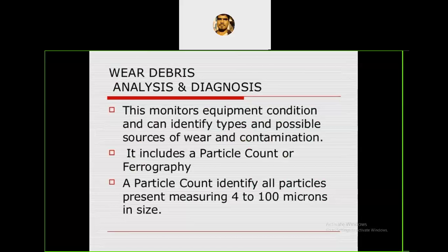I think you already did this in your sixth semester. What is the use of analysis? It will save a lot of time and also a lot of money, because physically we are not going to test the component. With the help of software, first we create the model, apply the boundary conditions, and check the stress distribution and the deformation.